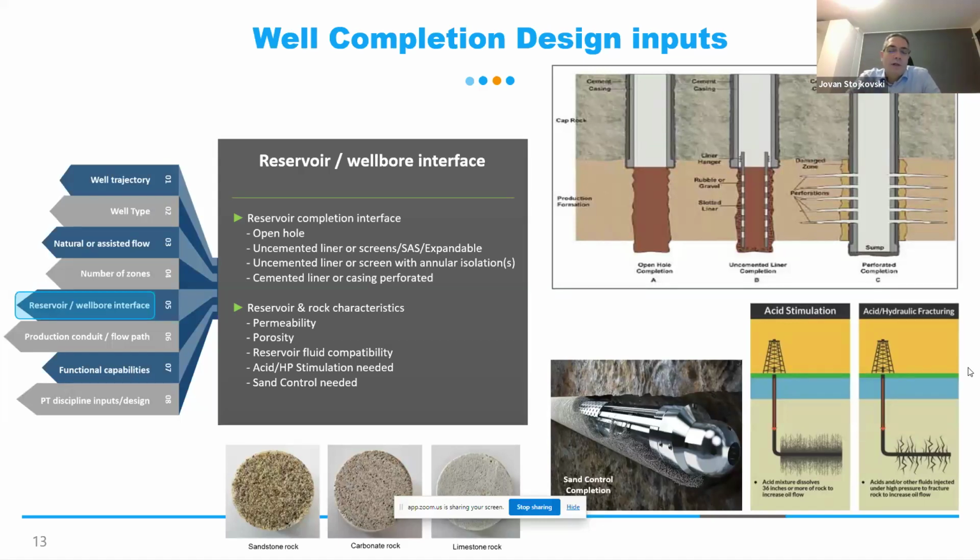Or if we are confident that we can drill and then place casing, cement the casing in place, and after that perforate, then we need to align with our completion how this will look. In some companies, the decision to run a liner hanger with standalone screens is also part of the completion engineer's decision.